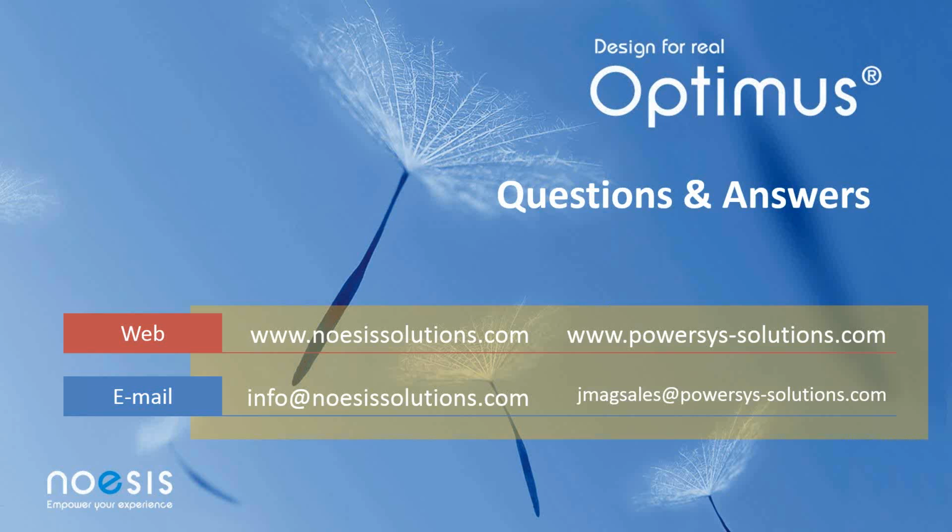Okay. Here's one over to you, Taylor. In what ways can parallel processing be utilized by Optimus? That's a great question. We didn't spend a whole lot of time today talking about it. Optimus has the ability to incorporate parallel processing in one of two ways. First, it can call the analysis tool like JMAG to be run on multiple processors. That's not a problem at all.